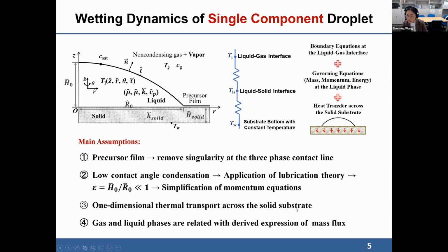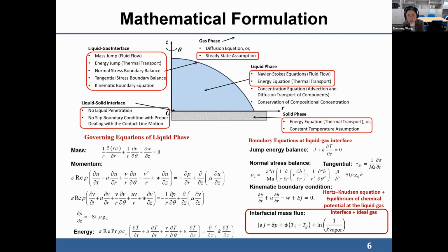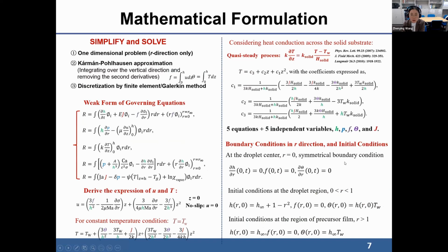Across the solid substrate, we consider a one-dimensional thermal transport process. We also derive the expression of the interfacial mass flux based on the Hertz-Knudsen equation. This is a summary of what we considered about the governing equations in the liquid phase, as well as the boundary equations at the liquid-gas interface. We additionally made some simplifications and applied some approximations, and the system is solved by the finite element method.